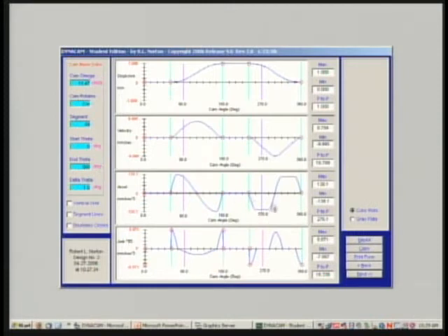Here's the characteristic shape of a modified trap acceleration. Here's the characteristic shape of a modified sine. The velocity is distinct in the case of the modified trap because of the straight line sides. The velocity here is a harmonic shape. The displacement functions look not at all different. Once you've integrated out these differences, they look the same.